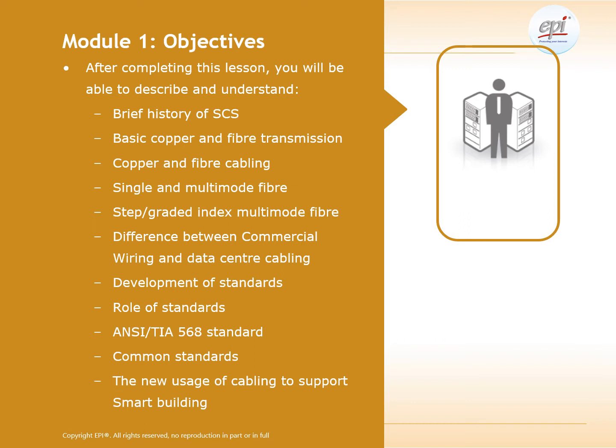But nowadays there are more new usage, say BMS, the building management system, smoke sensor, humidity sensor, or even PoE, right, power over Ethernet, lighting, access point, CCTV, so for the energy management system, etc., etc. Also the public address, PA system. So there are a lot of new applications that can also supported by the cabling system.